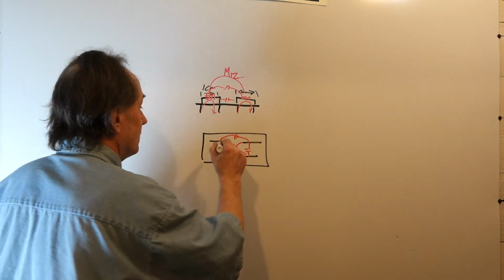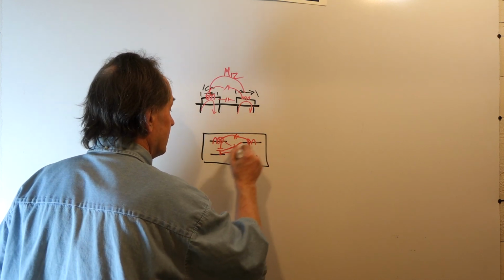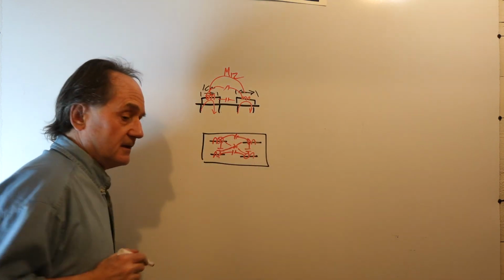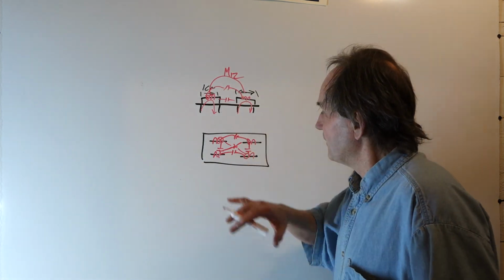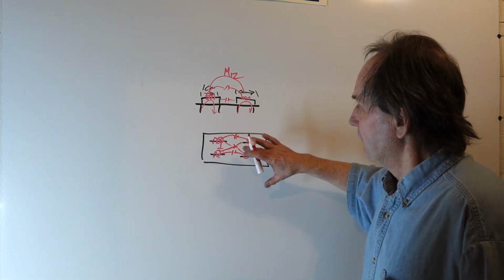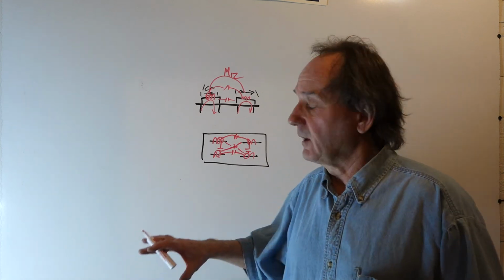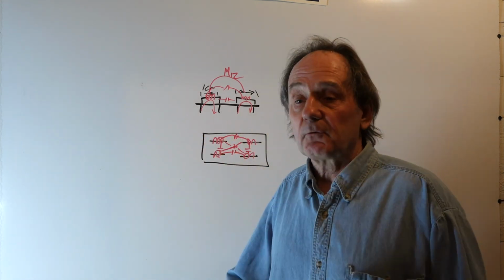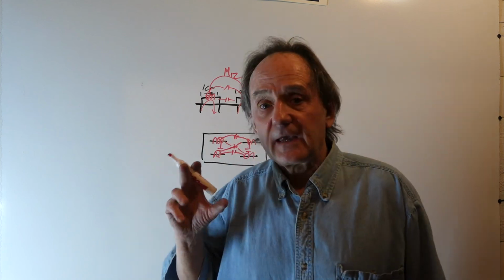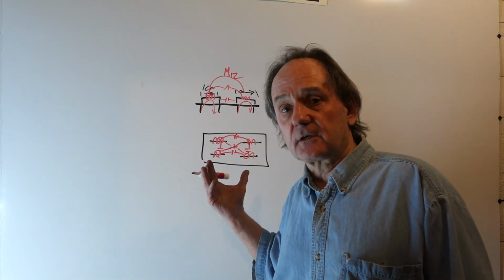And you have mutual inductance, self-inductance on each one of these. And to model these things gets to be rather involved. This is one thing I'm very successful at. I've modeled these things so that they're well up into the hundreds of megahertz range and get very accurate results in the modeling. Your CAD programs just can't do these things for you.